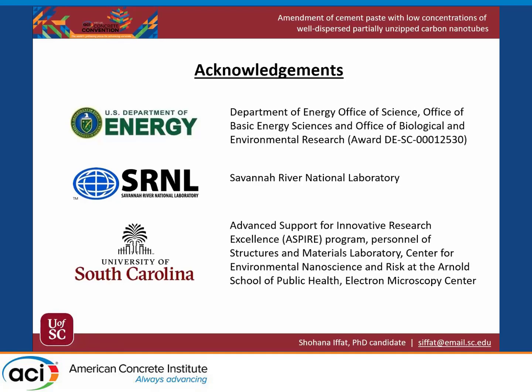Okay, that is a very good question. So why not graphene and why not multiwalled carbon nanotube? Actually, this is a hybrid structure in between multiwalled carbon nanotube and graphene nanoplatelets. If I can unzip the outermost layer, the comparable aspect ratio of multiwalled carbon nanotube can be achieved, which we cannot consider for graphene nanoplatelets, because if we fully unzip them, we will reduce some aspect ratio. Aspect ratio is also essential for mechanical enhancement like bridging the cracks and other properties inside the cement matrix. So partially unzipping will at the same time increase the open surface area and functionality, so they can help to precipitate more hydrates. At the same time, the mechanical enhancement can be achieved through achieving the comparable aspect ratio.